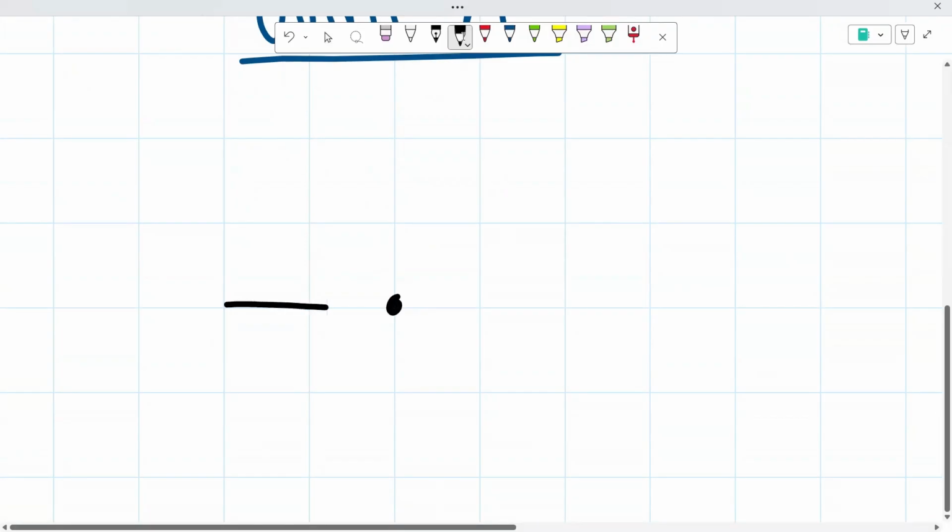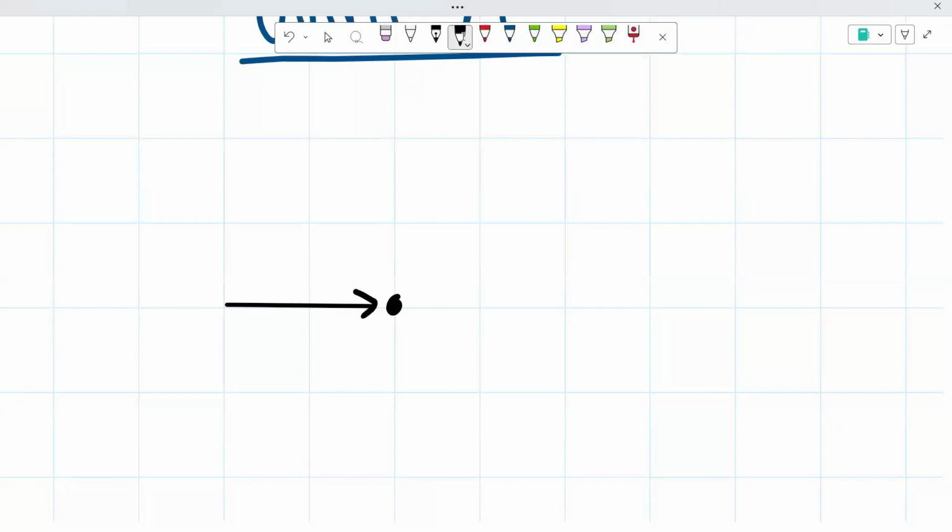From it, we would have our reaction. It doesn't really matter the direction of it. We just do know that there is that reaction. And then from there, we would have our member AB. I'm going to assume that with tension. And then from there, we would have our member AE. So these are all the forces and reactions that are found at joint A. So from this, we're going to look at it and see if it could fall in any of those special cases that give us zero force members.